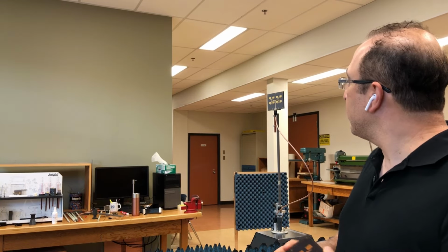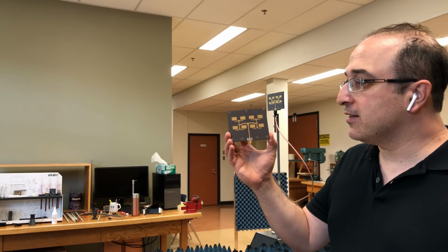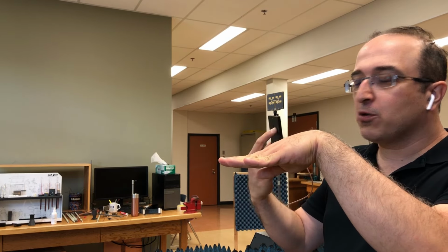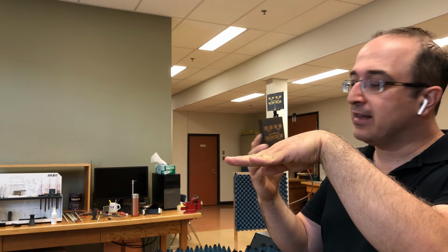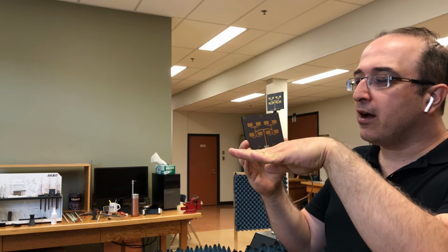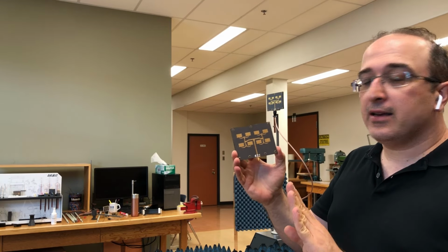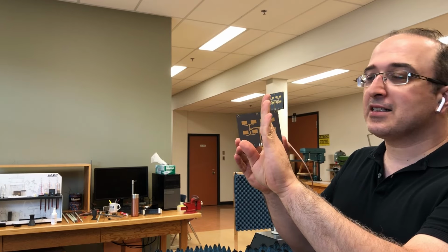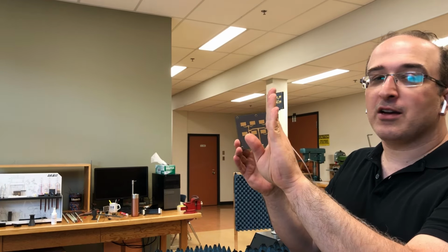Okay, so right now the antenna is mounted like this. As you remember, this was H-plane, so when you rotate like that, you collected the H-plane cut. But now remember that E-plane from our previous discussion is this plane. Now, using this system, you cannot rotate your antenna in this plane.